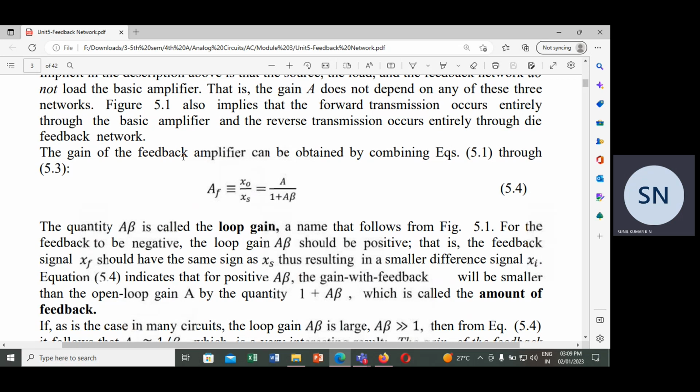But if we employ non-inverting configuration, inverting configuration or voltage follower configuration, in voltage follower the gain will become unity. But in non-inverting amplifier, 1 plus RF by R1. In inverting, RF by R1. So this corresponds to what? This is negative feedback configuration.